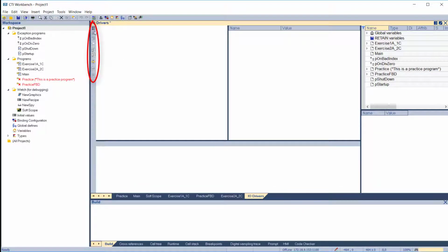The icon toolbar on the left is used for building and editing the configuration. These icons allow you to add a new configuration, master port, slave data block, and variable. The move up and down icons allow you to reorder items. You can temporarily disable an entire configuration here, which removes it from the runtime but keeps it intact for later use. Finally, you can sort items using this icon.